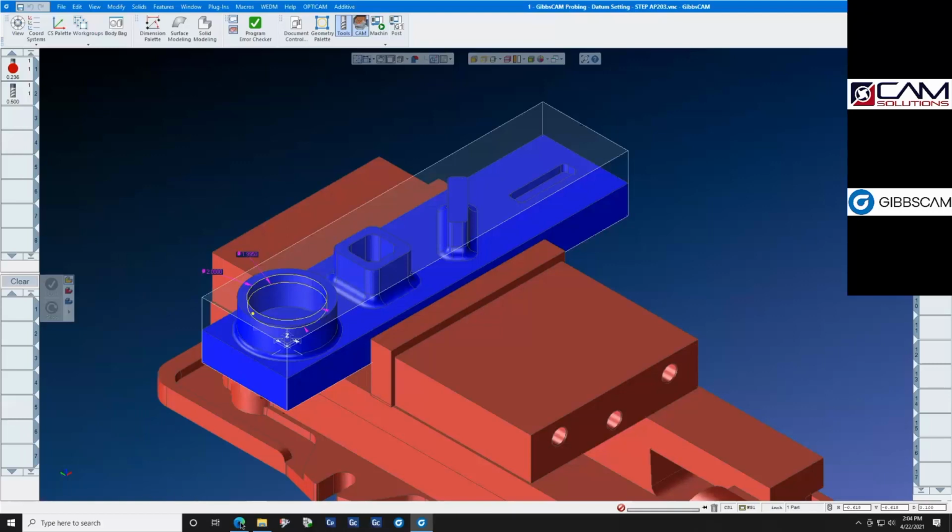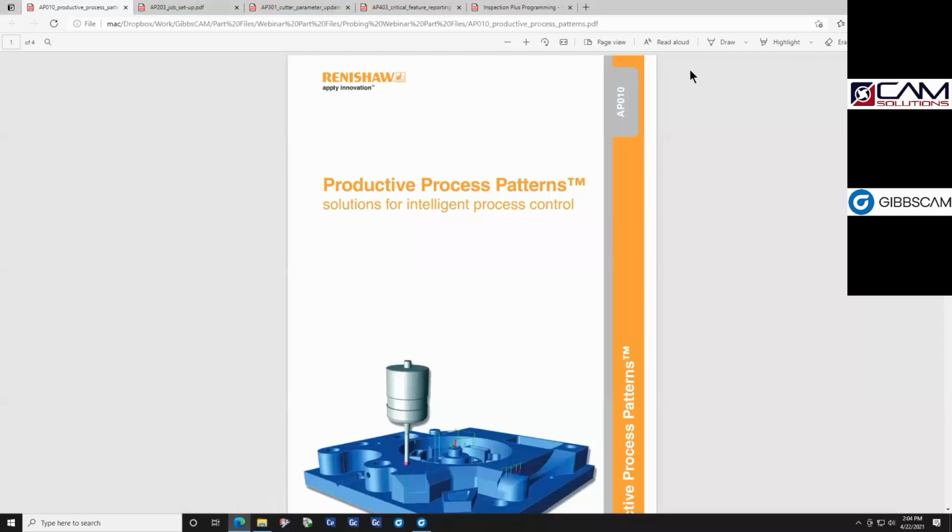If you're not aware of this, setting the datum of the part is part of the step application system of CNC management. And yes, when you purchase this software option from GibbsCAM, you will purchase the GibbsCAM probing option, and you will also purchase a post processor upgrade for each post that has a machine with a probe in it.